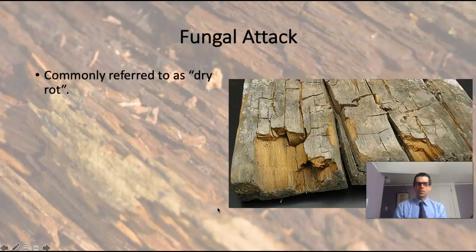All right, we're getting into some scary stuff here. Fungal attack. The term is dry rot. We'll talk about why it's called dry rot. But everybody uses dry rot as a uniform term for any sort of wood decay, but it's very specifically referring to fungal attack. Okay?